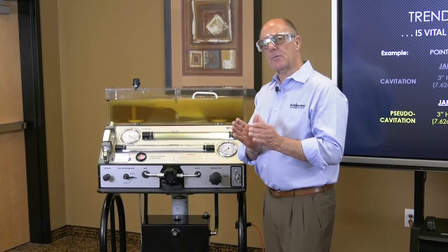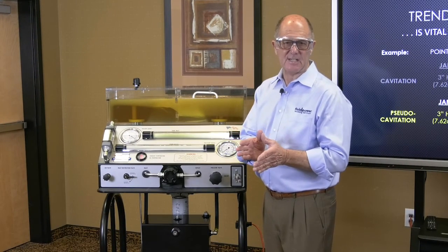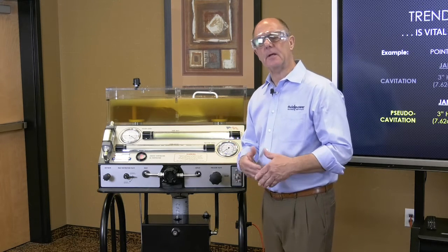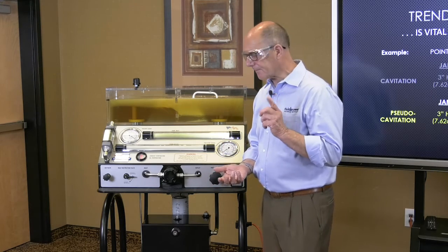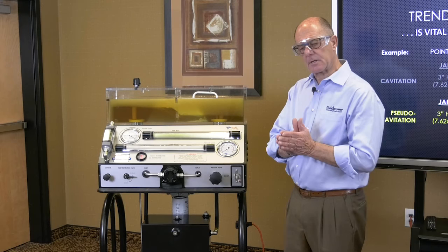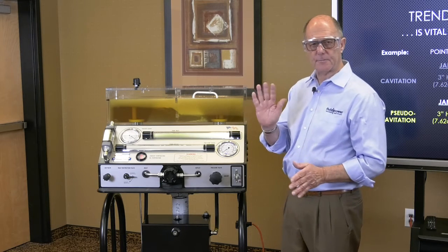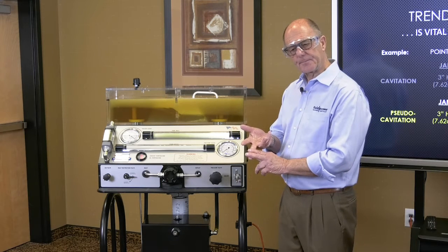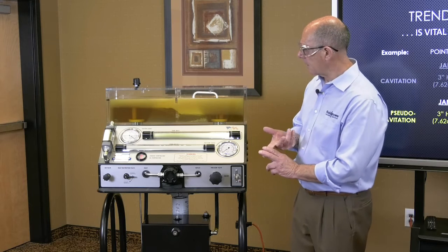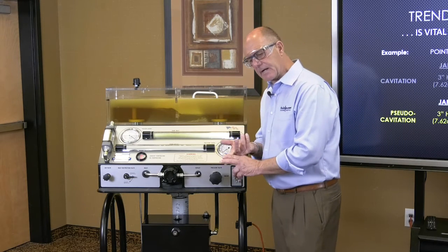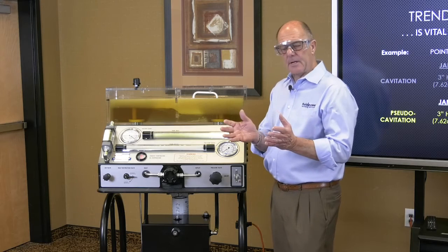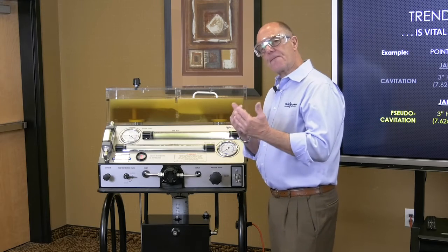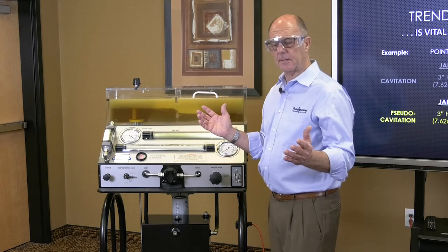Every piece of contamination we feed into a hydraulic system is an abrasive seed, and its growth is exponential. Today it's 1, tomorrow it's 10, the next day it's 50, and so on. However, it doesn't affect the purpose of the oil in its entirety, meaning hydraulic oil has four purposes: I transmit power with it, I seal with it, I lubricate with it, and I carry heat away with it. So when the pump is cavitating, the only damage, and I'm not undermining how serious that is, doesn't affect the purpose of the oil throughout the system.